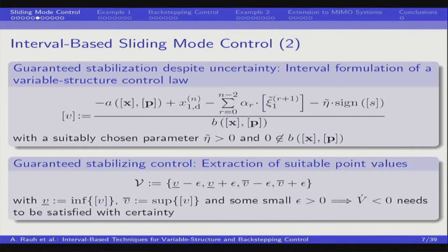We are evaluating a sign function of something that is uncertain. In the near surrounding area of our control goal, we're usually not able to distinguish if the control error is positive or negative. That means the sign function is deactivated when we cannot specify the corresponding sign, so the sign function just becomes equal to 0 in this case, and we're just using the regular control strategy on the left-hand side, which is just a dynamic feed-forward control in this case.